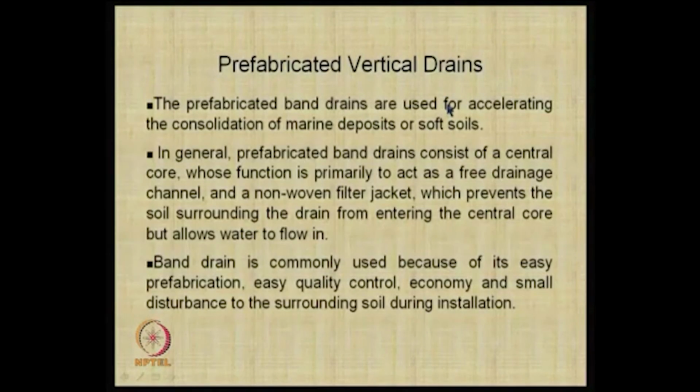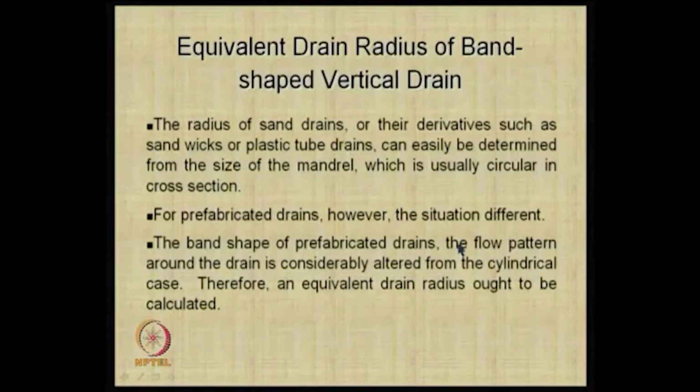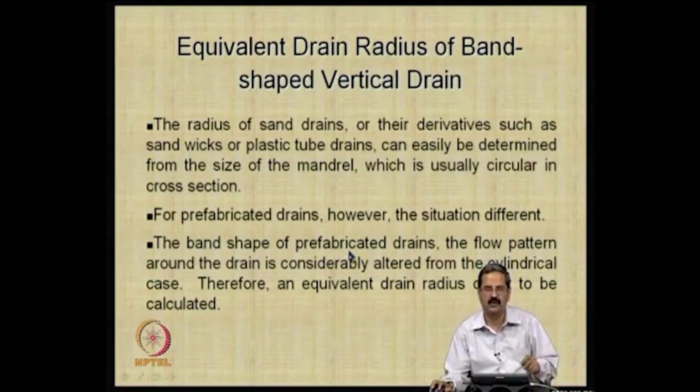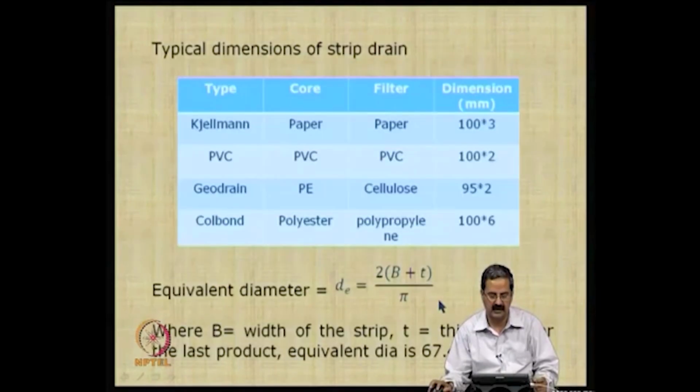As I just mentioned, PVDs are much more comfortable to use because of the ease of fabrication, quality control, and economy, and sample disturbance to the soil is very little during installation. This is another important point one should realize: earlier we had an equivalent diameter, and now, since the shape of the drain is more of a rectangle, the flow pattern around the drain is considerably altered from the cylindrical case. So, you have to calculate the equivalent radius.